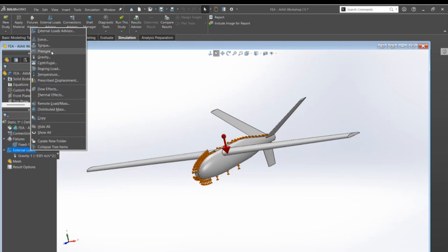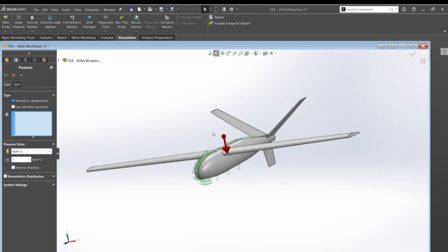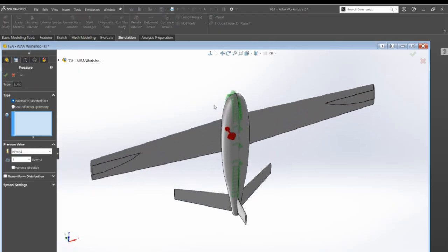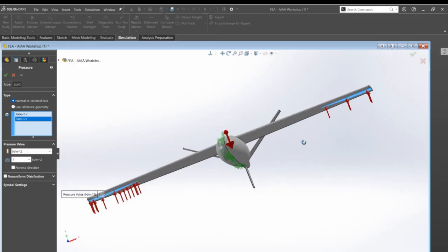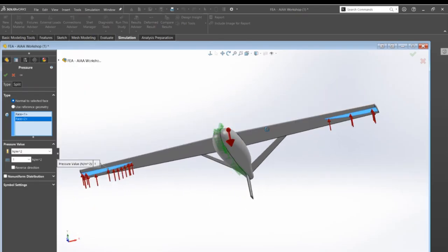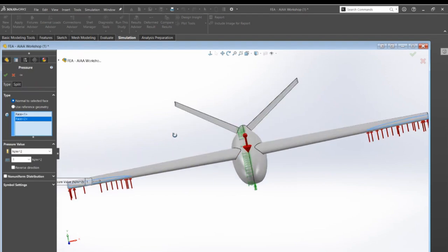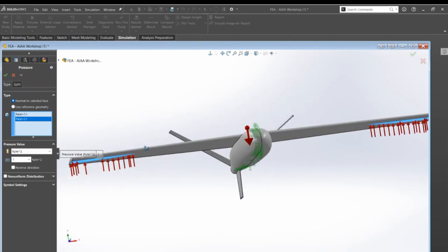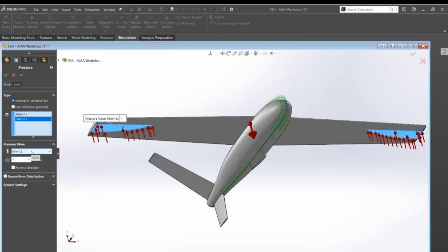And we're going to do pressure just because, as you say, we're in a 60-degree bank angle turn. We've got 3 Gs of force, and that's going to put some pressure on our wingtips. So if you look under the plane, there's actually these 2 surfaces that I've put in here that we can select. And this is just going to model basically the edge of the wingtip. In reality, this force would be distributed evenly along the entire wing, but this just makes it easy for us to select it. So go ahead and select those 2 forces, and then we need to assign a value to it.